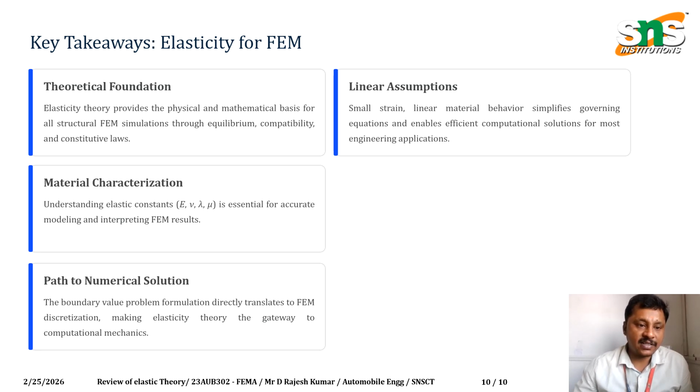So let us summarize the key takeaways. First, elasticity theory provides the physical and mathematical foundation for all structural FEM simulations through three core principles. They are equilibrium, compatibility and constitutive behavior. Second, understanding elasticity constants, Young's modulus, Poisson's ratio, etc., is essential for accurate modeling and interpreting the FEM results.